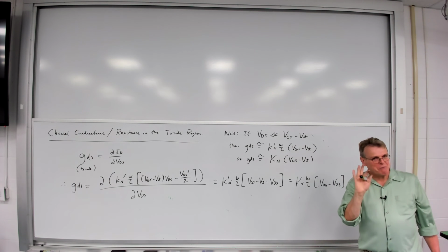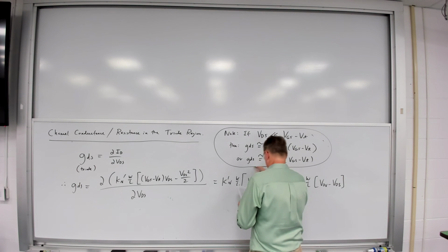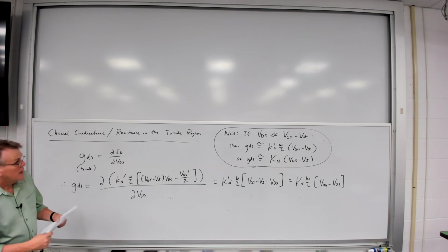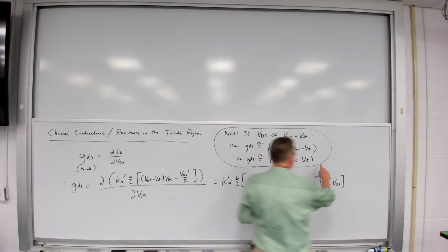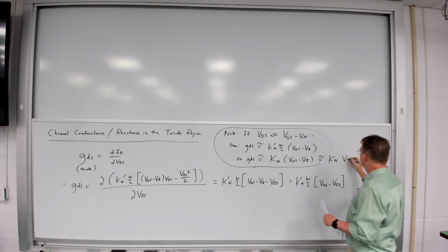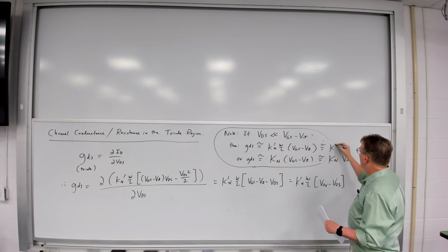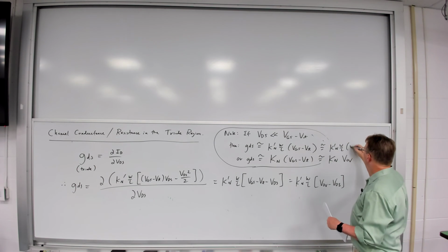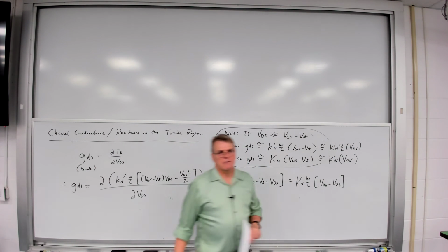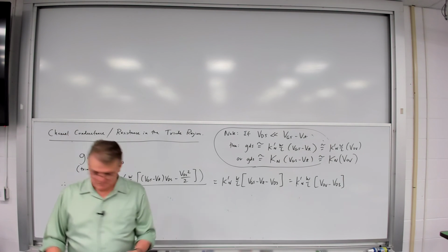I didn't want any confusion to arise. And of course, I can always say that each of these is approximately equal to K prime times VOV, and this is approximately equal to K prime W over L times VOV. So I can use the overdrive voltage instead, once again just using the definitions from the text.